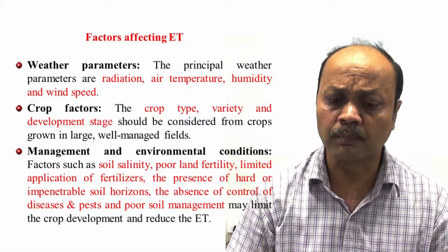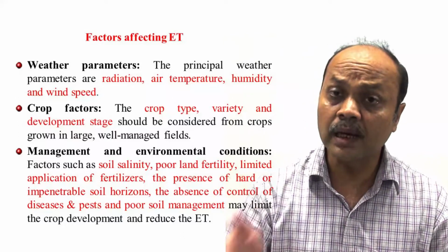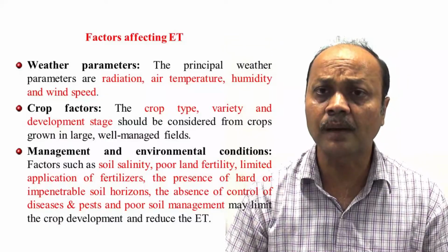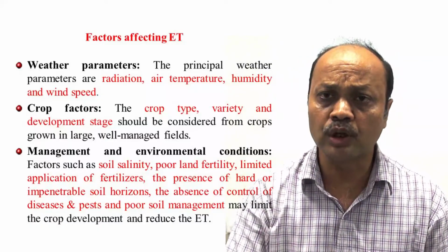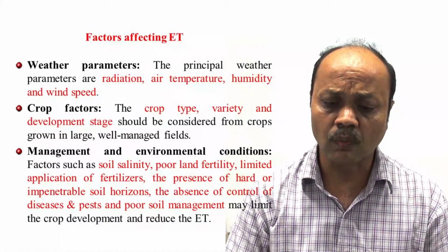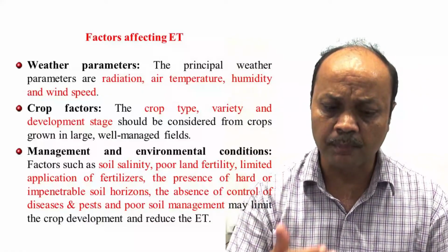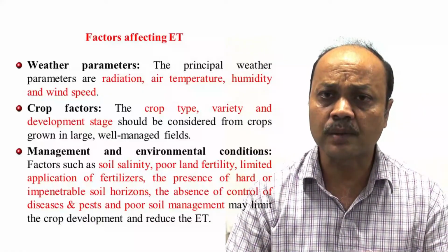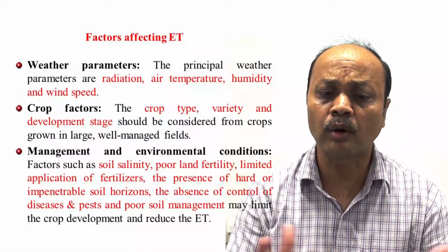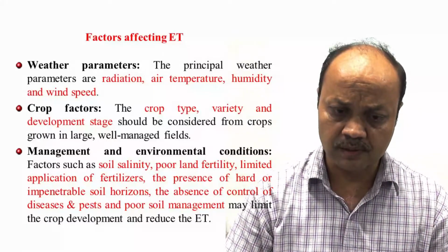Which type of crop you are talking about, whether it is tomato or brinjal, matters. Even in the same crop the variety also matters. And apart from that is the development stage; it is very clear that at each stage of crop development, your crop water requirement differs. Then there are management practices and environmental conditions, meaning what your soil fertility condition is, what the application of fertilizer is, what the condition of the soil is. There are various factors that come under management and environmental conditions that affect your overall evapotranspiration. So these are the three factors that affect your evapotranspiration.